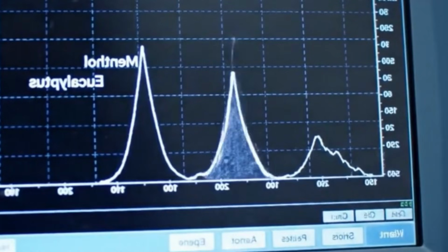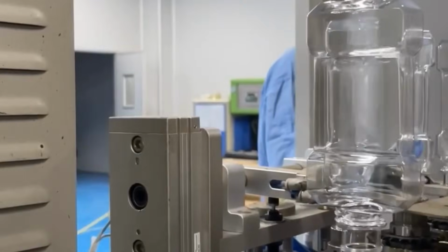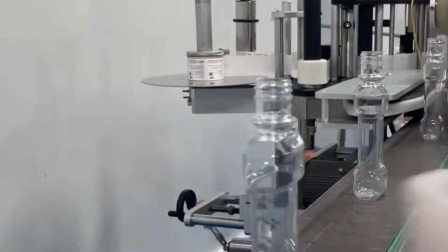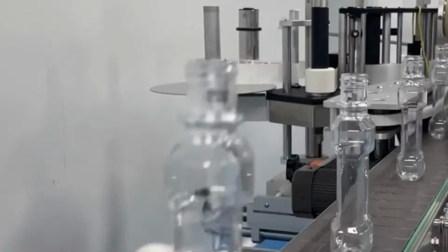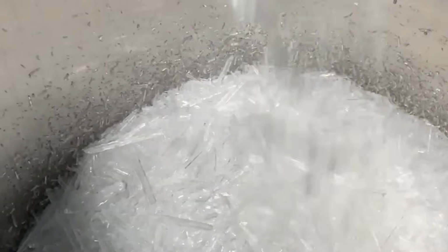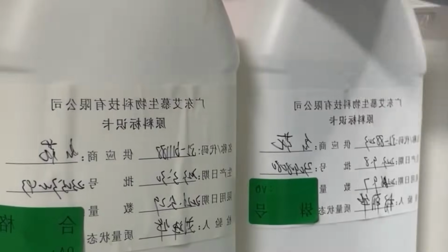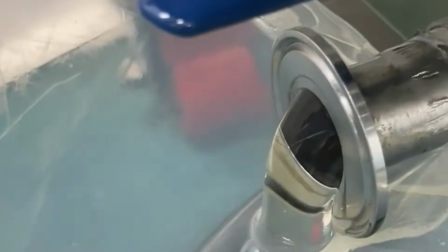Flaps are closed using hot melt glue or tape, and cases are labeled with shipping information using print and apply labelers. Completed cases are transported to palletizing systems. Robotic palletizers stack cases layer by layer using vacuum grippers or mechanical forks. Slip sheets are inserted as needed. Stack configurations follow warehouse layout and transport requirements.